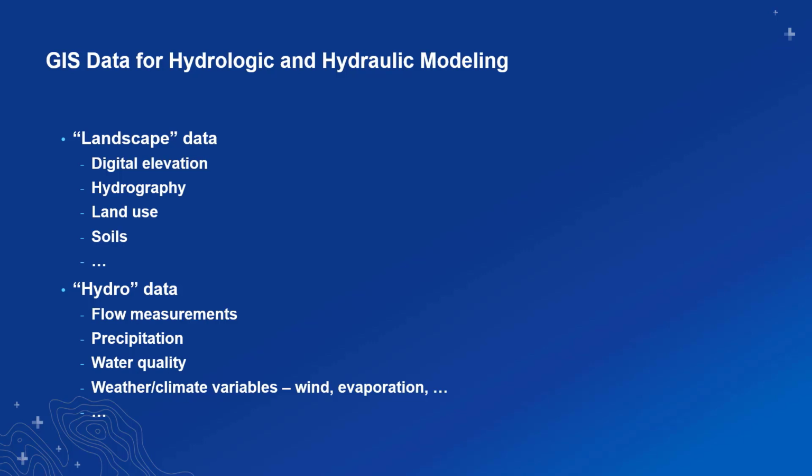And that goes across all the data used in analysis, not just one data set. Also, the quality of the data need to be put in the context of the type of the analysis being performed. For example, while for hydrologic analysis coarser data might be adequate, for hydraulic analysis we might need better data.